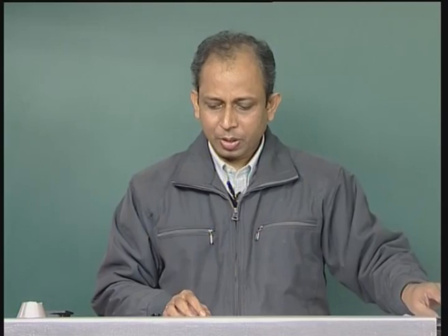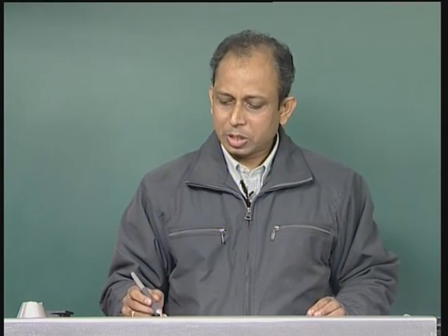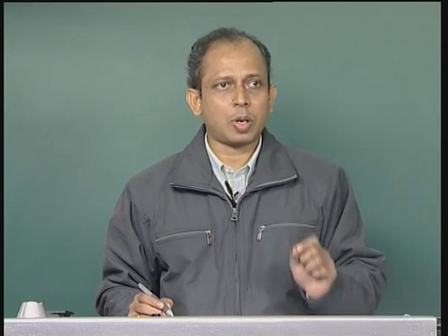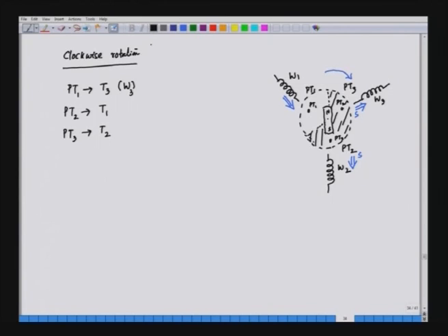Now, if we come back to our discussion here, as the rotor rotates, the stator field goes on shifting. So, as a result we have a drawback, and the drawback is the torque pulsation. Now, if we see the expression for the torque, torque is equal to K psi 1 into psi 2 into sine of the angle between them, so sine of gamma.